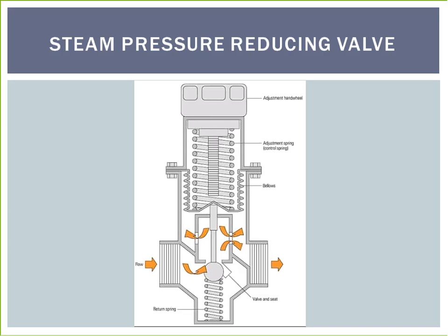In a steam-using plant, steam is often generated at high pressures and reduced locally to provide heat for each steam user. This is usually done to minimize the diameter of steam distribution piping and enable more cost-efficient steam delivery. A common way of lowering pressure is by throttling down the size of the steam passageway.